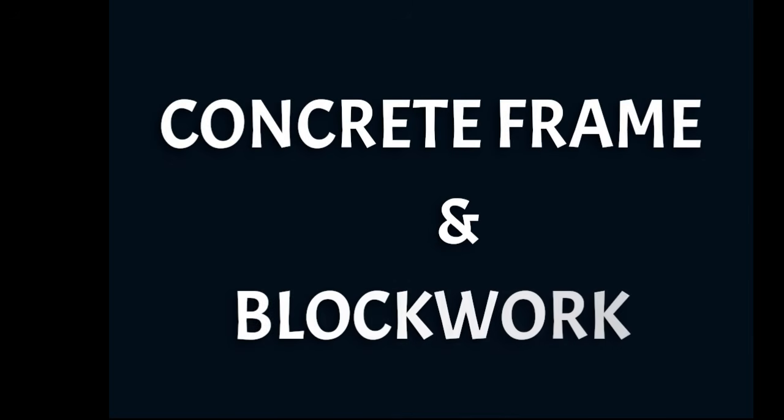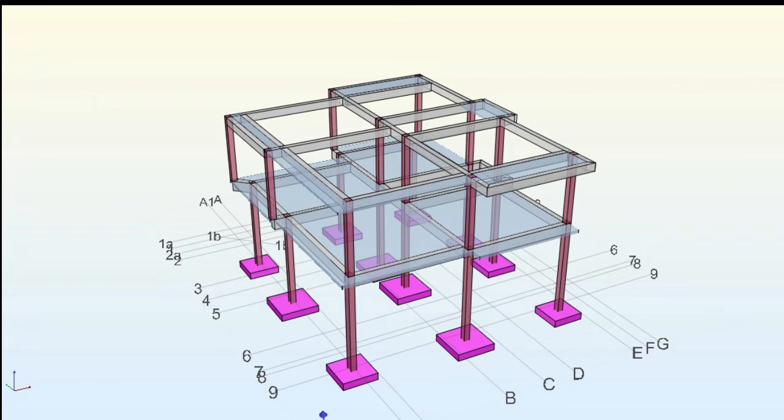Next is stages 2 and 3, which were combined. Stage 2 is concrete frame, and stage 3 is block work. Now, the concrete frame consists of the slab, the beams, and the columns that support and transmit all the building loads to the foundation, while the block walls act as partitions for the structure.